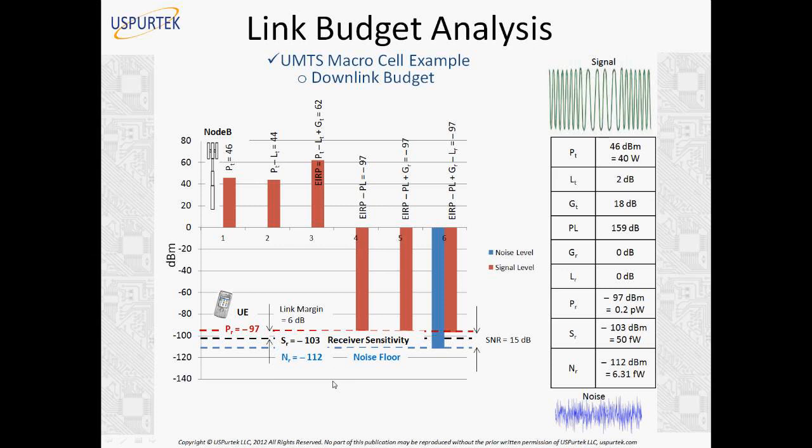Now in this situation, when the link margin is lower, what can we do? There are several solutions we could use. One is a very simple one: reduce the range of the cell. From our calculation, we find that for 8 kilometers distance, our signal level is very weak, and no handset can deliver a reliable quality of service. So then we say, okay, it's not 8 kilometers, it's 6 kilometers or 5 kilometers, and we'll have another cell after 5 kilometers. That is how RF planning works.